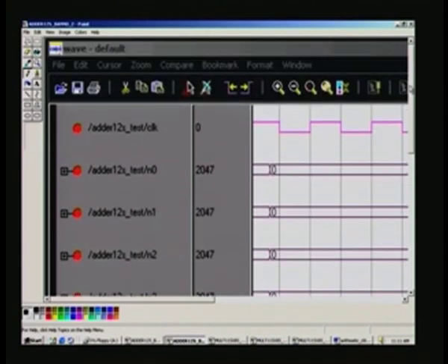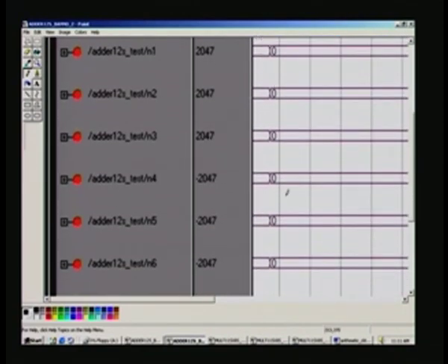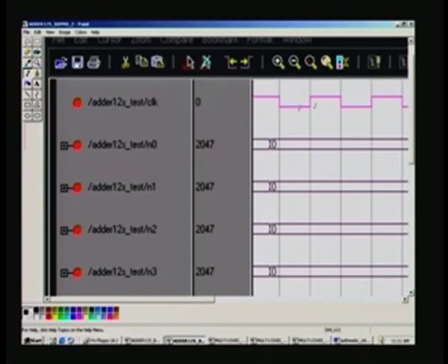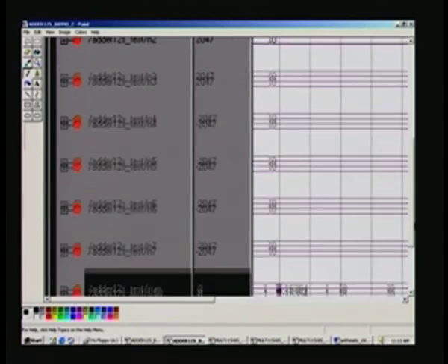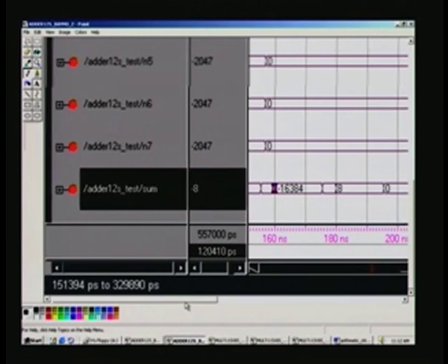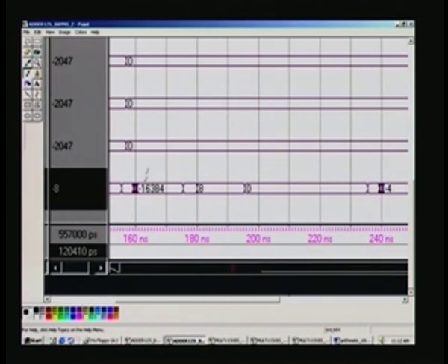So once again, some more of the last data, all of them are zeros, and the first one is the clock, and the final sum is here. We have already seen minus 16384, just overlapped so that you will have continuity in visualizing this. So the next one is 8 into 1 as per my list, and it should give a sum of 8, that is what we have here. And the next one is 4 into 1 minus 1 into 4, that must produce 0, that is also there.